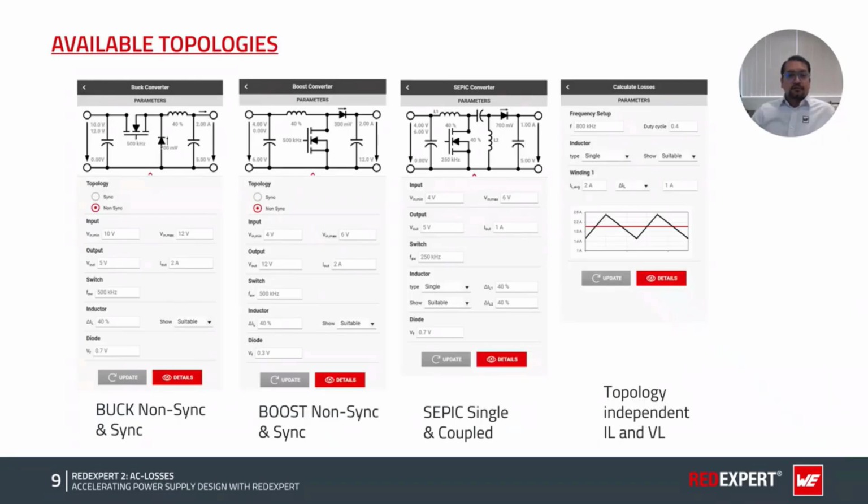REDEXPERT supports a wide range of converter topologies, not just the common ones. It supports buck and boost in both synchronous and non-synchronous modes, SEPIC for both single and coupled inductor variants, and a topology independent mode where you input the inductor current and the voltage directly. And this last option is especially powerful for engineers who are working with custom topologies that don't fit into the standard converter topologies.